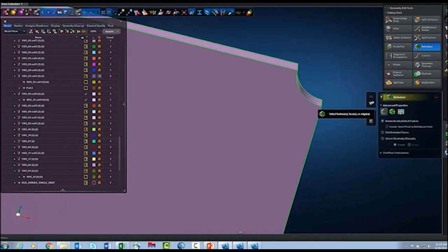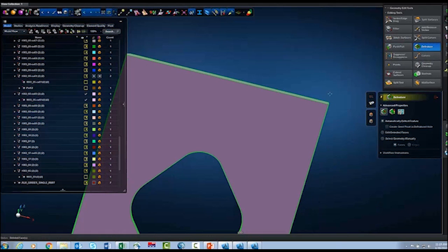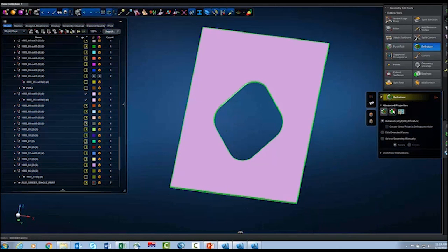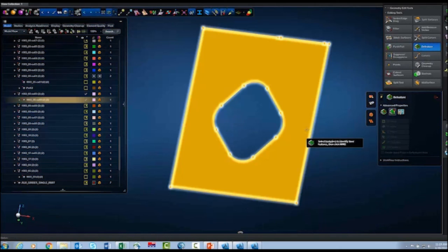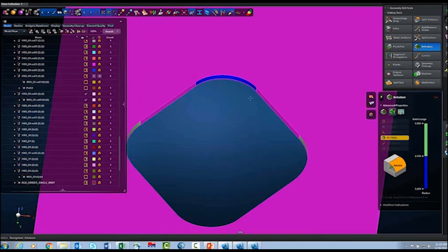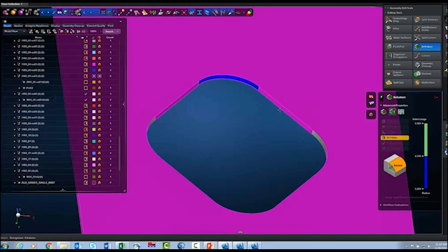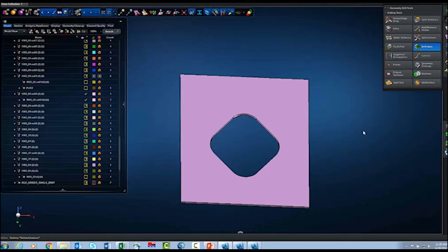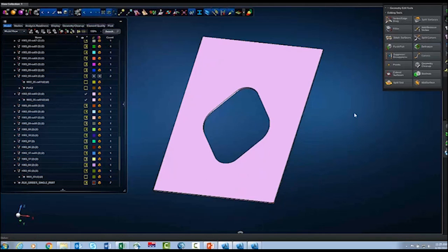We can defeature things by just clicking on them and they go away. I know you're probably saying, but Larry, I've got thousands of those. I don't want to click on all of those. Well, we got that covered too, because we can select either an individual part, or we can select the whole model, and Apex will identify the features for us. I can actually select those features and remove them very quickly, once again, whether it's for individual parts or for the entire structure. In this case, I'm going to do an undo. We've got multi-level undo here, so I want to keep that, so I'm going to bring that back.